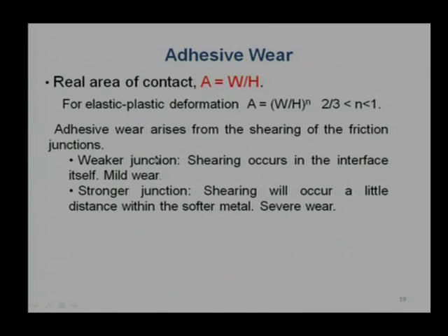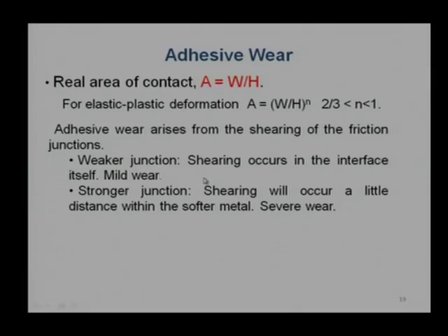An interesting thing is that it is very difficult to find out the shear strength of the interface, particularly when a few asperities are plastically deformed and a few are only elastically deformed. We know very well that to shear a plastic junction we require more force. To shear an elastic junction we do not require much force. That means we need to count at every asperity what the shear strength will be, which is a very tedious job and is highly statistical.